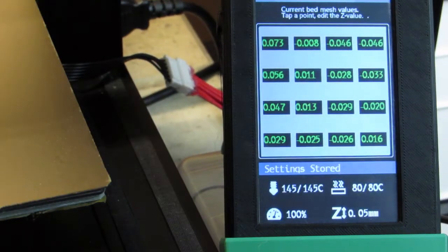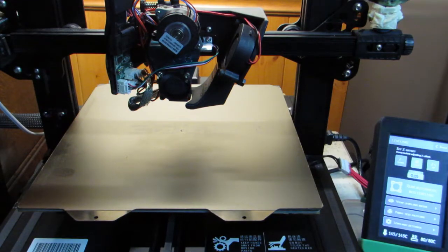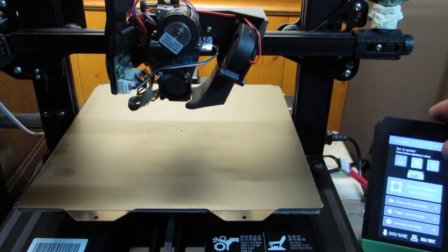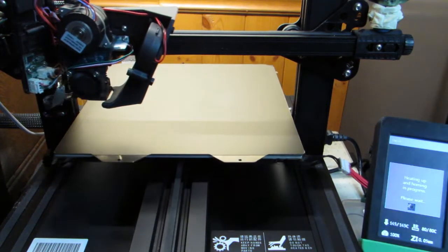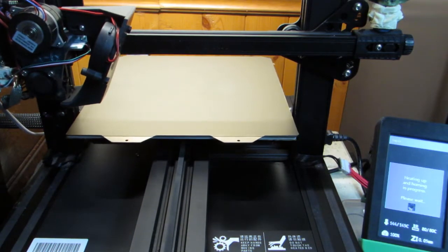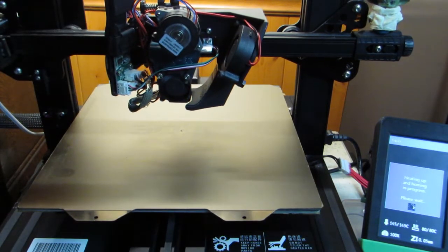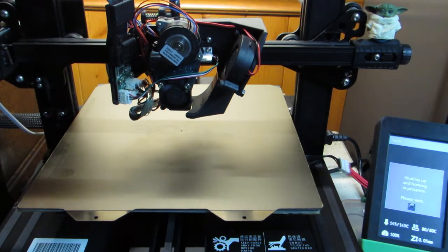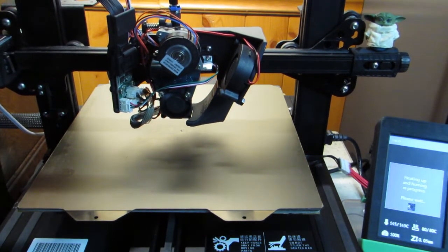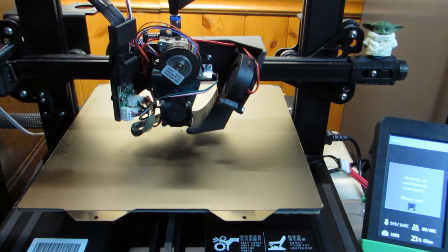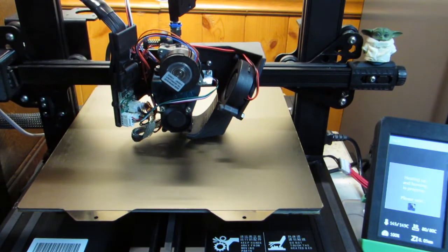So there's your bed mesh, ready to go to print at that temperature on the bed. Remember, my experience on this printer has been that offset varies from time to time. So that risk is always present in my mind. So if I home using the Z offset button, again it uses the same leveling settings, so still too cold for the filament to be drooling.